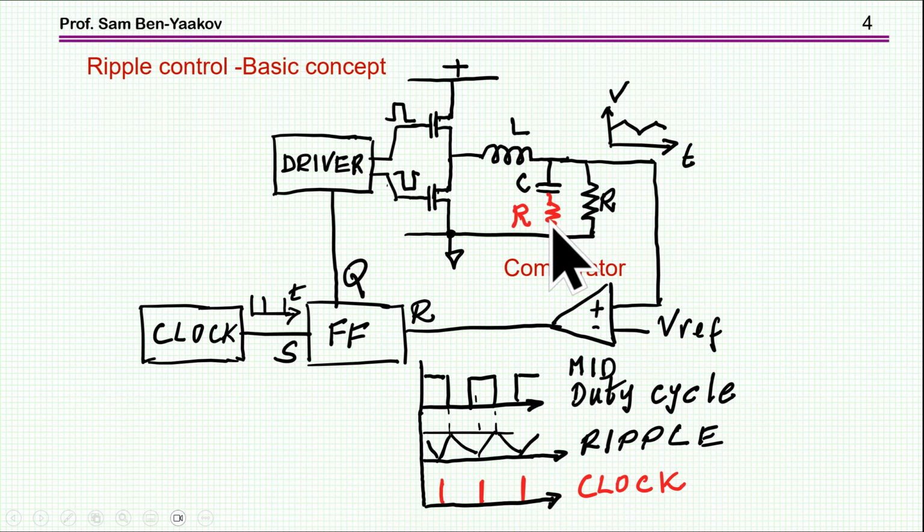I mean, the upper transistor will stay on until we reach again the peak value of 1 volt at the sense point. So the response is really very nice, and this is one of the advantages of this approach, which is, I should say, I didn't say it before, this concept in a variation of it is used in many commercial PWM controllers.